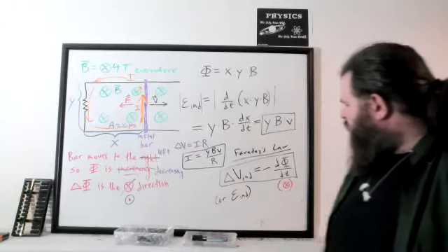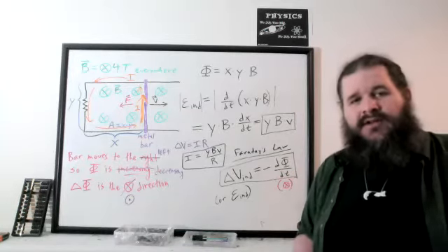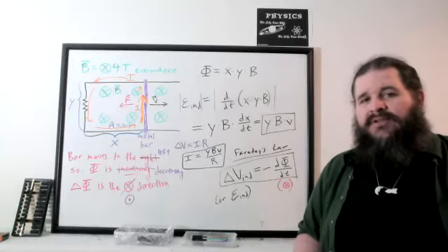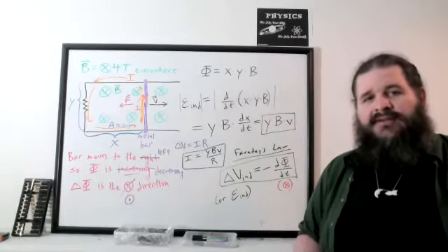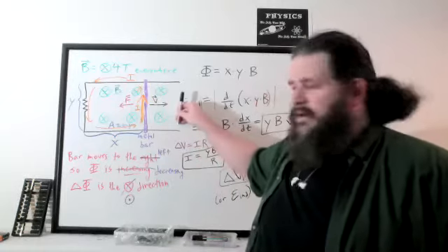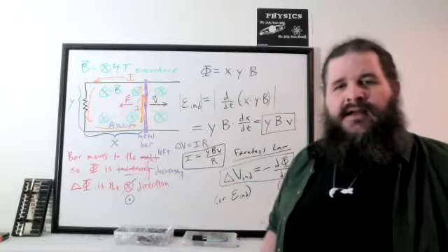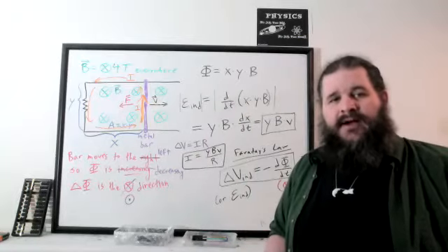And this really goes back to the meaning of this negative sign here. The negative sign means the end result acts in a direction opposite to the change that's causing it to happen in the first place. The change is the bar moving to the right. The end result involves a force pushing back to the left. It's acting to slow itself down.